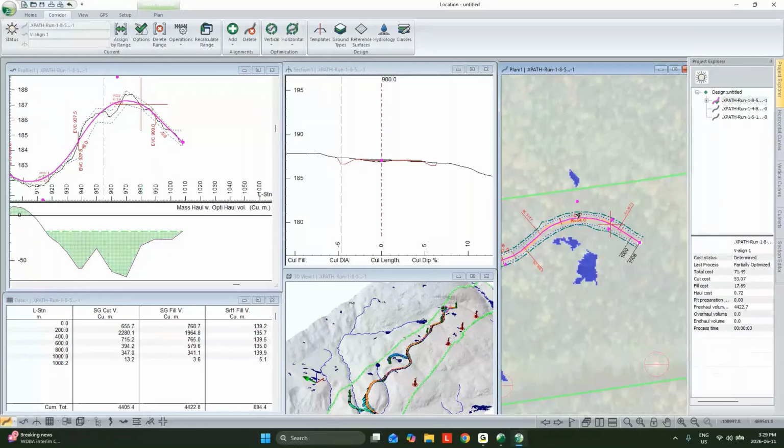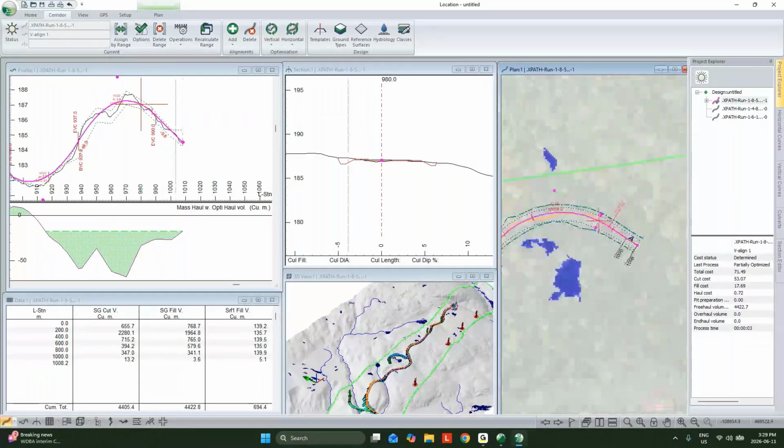So there's all sorts of different ways we can tackle our pads or work sites. And we could do the pad as its own standalone entity in terrain if we wanted to. Or we could do something a little more complex like we do in our standard wind farm design workflow, where we basically position these relatively complex geometries for the pad laydown, and that has a boom area, areas to store things. So we could do that. But in this case, anticipating just a rectangular pad being the best fit for the site, I'm going to use an override.